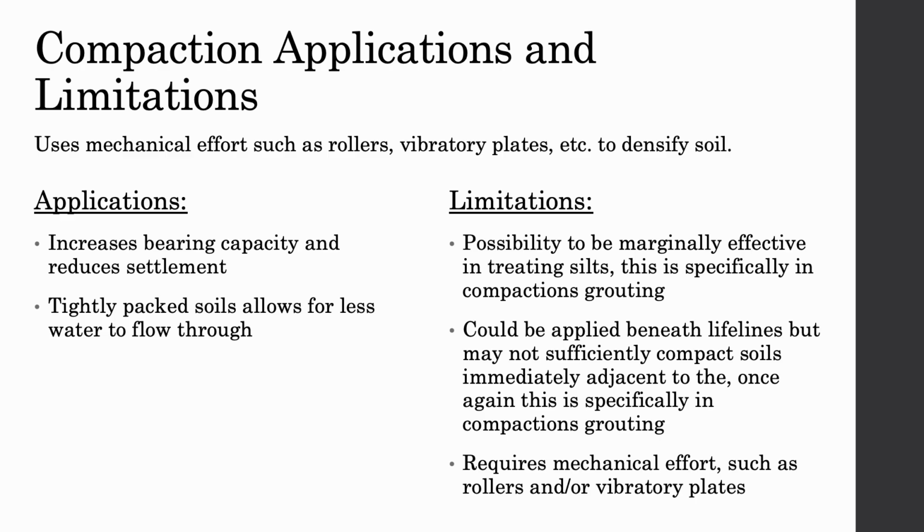The limitations of compaction include the possibility of being only marginally effective in treating silts, and this is specifically in compaction grouting, as well as that it could be applied beneath lifelines but may not sufficiently compact soils immediately adjacent to the lifelines, and once again this is specifically in compaction grouting. Furthermore, another limitation of compaction is that it requires mechanical effort such as rollers and or vibratory plates.